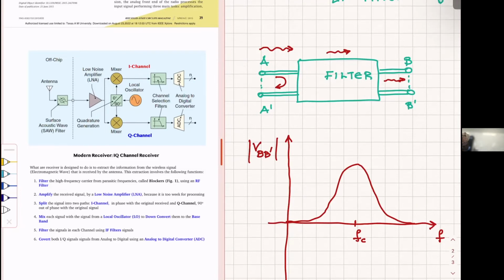Why is transmission important? You could say, if I know the reflection, then I know the transmission. Well, only in magnitude, because the power is conserved if you assume there is no loss here. But for a voltage that has both magnitude and phase, the transmission coefficient is important to show you what is the phase of the signal here. So you have to characterize this and this.